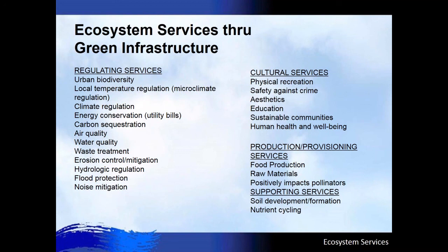We're not going to go through them all, but it's interesting that normally for stormwater facilities, the only services that we normally design to are 3 of them: the water quality, erosion control mitigation, and hydrologic regulation, and sometimes flood protection as well. But it's interesting that when you go from single functioning stormwater facilities to green infrastructure, all of the additional benefits that can be acquired.